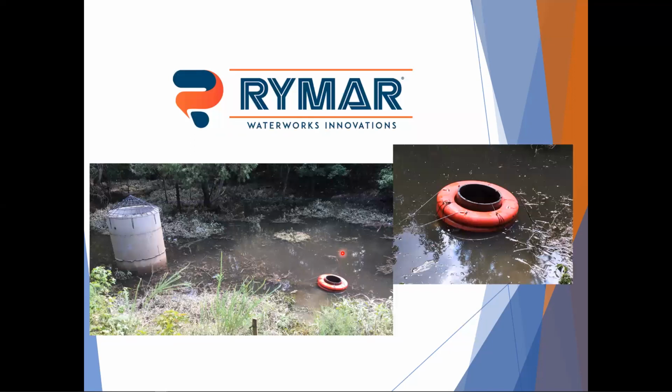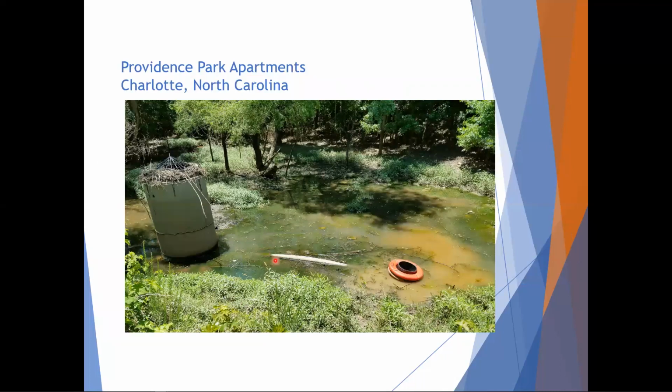We've kept an eye on it, keep watching it. It is in a natural stream, so sometimes if the flow rate's there, it has a little bit of a permanent pond, but if you get a couple of days of dry weather, it'll dry out. One thing we did find after about 4 or 5 years is the pipe here, we had put in an HDPE pipe, and for UV, HDPE started to bow and bend a little bit.